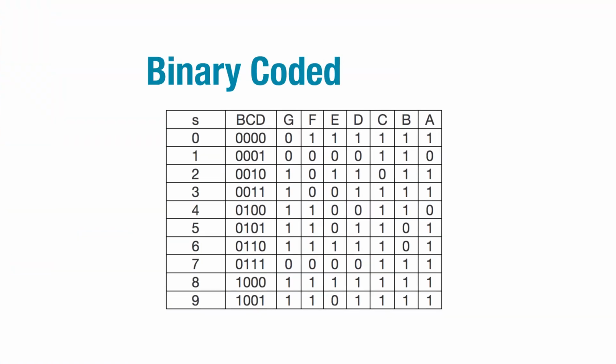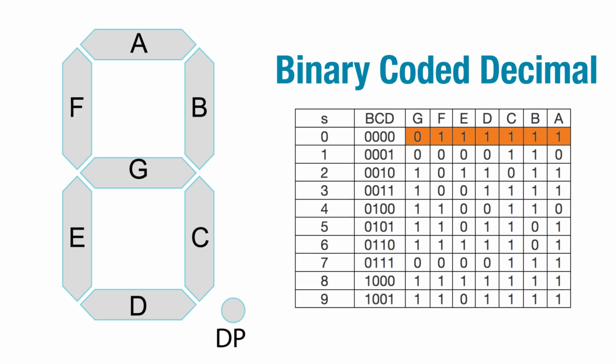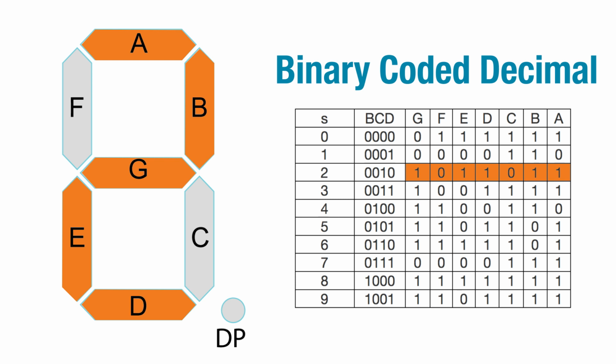In the last episode, we discussed how BCD is converted to 7-segment. BCD is binary coded decimal, a 4-digit version of binary. So this type of decoder translates 4-digit binary to 7 signals that control the LED segments of the display. So if we want to display a 2, we input a 4-digit binary 2 into the decoder, and it outputs signals that turn on the appropriate segments to display a 2.